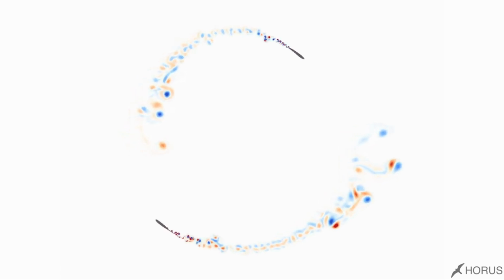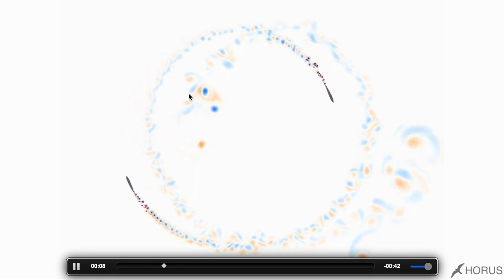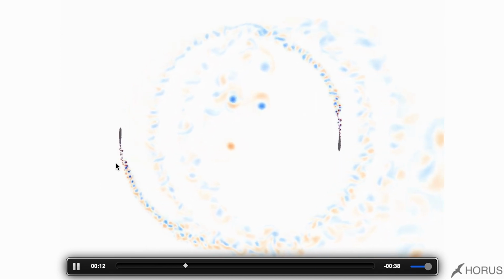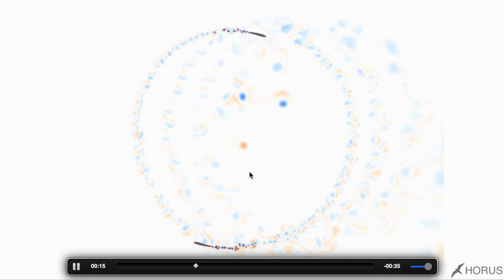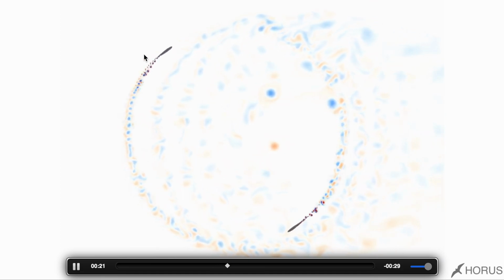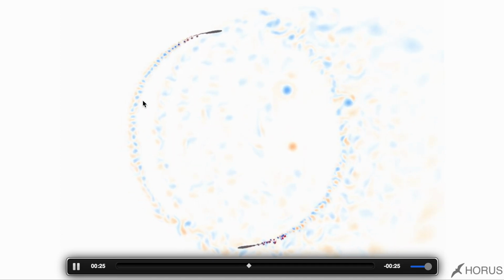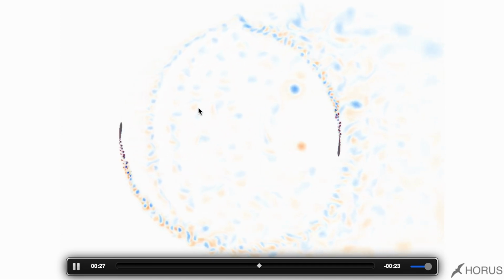It's an example of a vertical axis wind turbine. So here you're taking a top-down view of a slice through a vertical axis wind turbine. You can see the vortices that are shed by each blade of the turbine and how they interact with each other downstream. It's not shown here, but this is actually an adaptive simulation, so the solver is tracking these regions of vorticity and using high solution polynomial degrees in those regions where the flow is rapidly evolving.